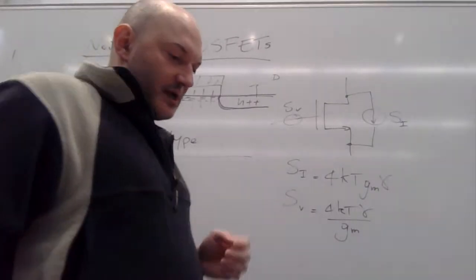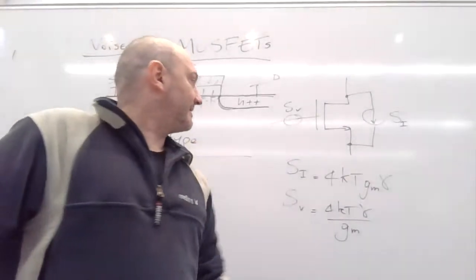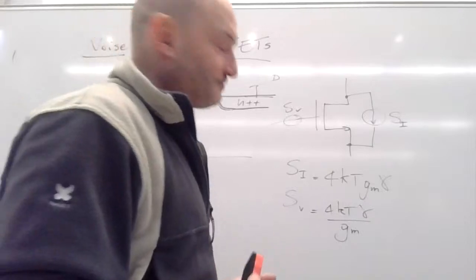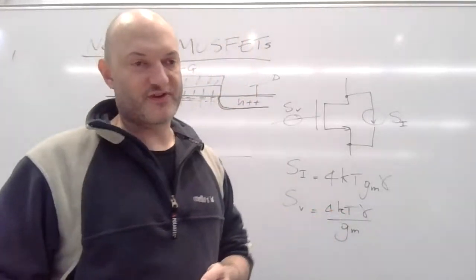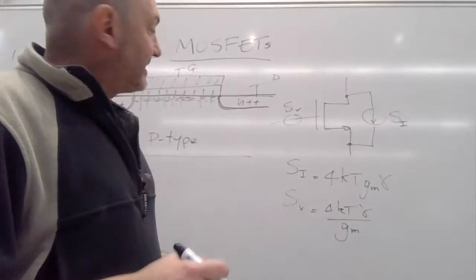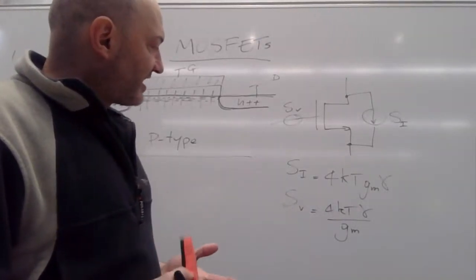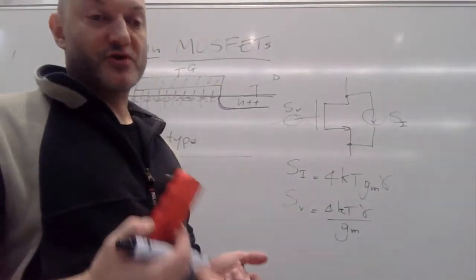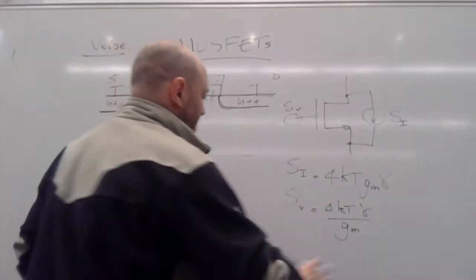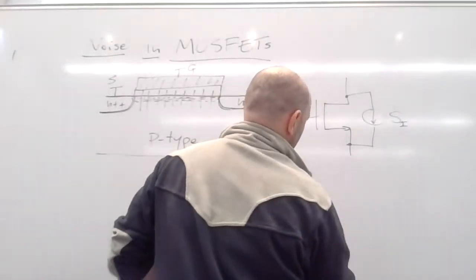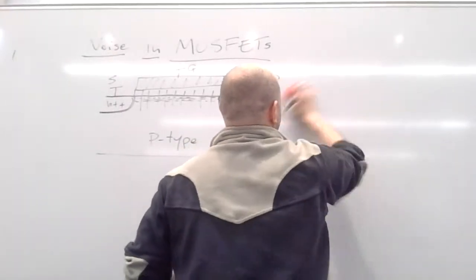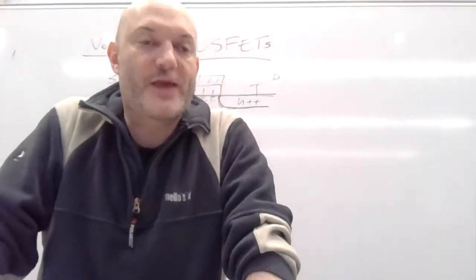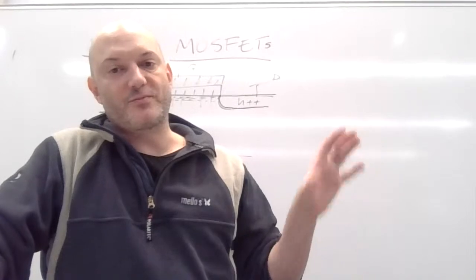The circuit we are going to see now, and the only one we are going to see today, is the differential amplifier. Why the differential amplifier and not something else? Because the differential amplifier is often the first stage in a more complex amplifier or a more complex circuit. For example, if you remember our simple operational amplifiers, we had a differential amplifier followed by a common source amplifier.